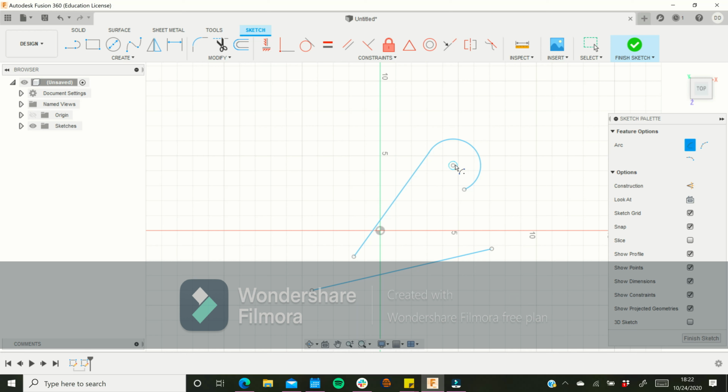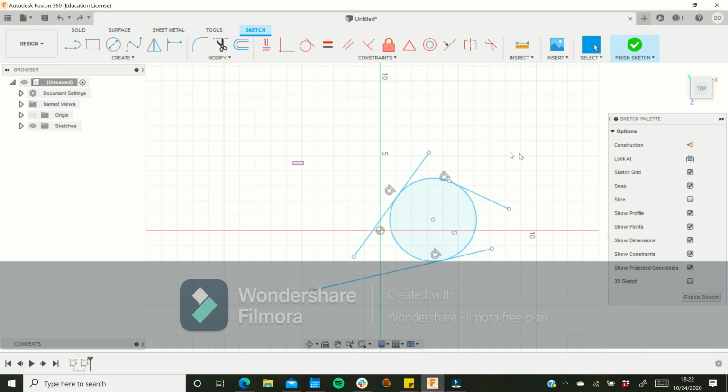But as you can see, the arc is always constrained, or always limited, I should say, by the radius and the center point. So if the center point isn't right in the middle or isn't compatible with being the complete width of the arc that you want, then the radius won't be able to stretch that far. I hope that makes sense. It's a bit confusing, but it's simple. The more you play with this sort of stuff, the more you'll get used to it.